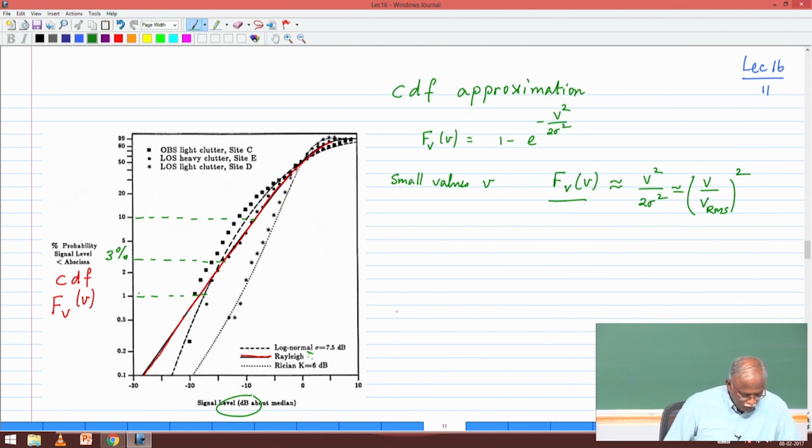Okay, now I would like to also introduce you to another very important aspect, and that is the notion of how we work with this. Basically, I want to relate the fact that now we understand that the small scale fading is going to cause dips in the signal. How bad are those dips? We can look at the CDF and we are going to tell. Now the question is, previously we allocated some margin in my link budget for the shadowing.